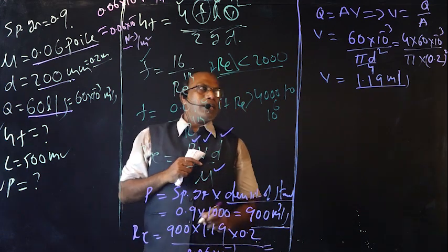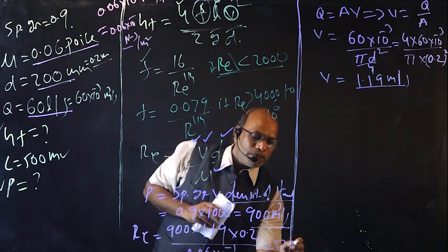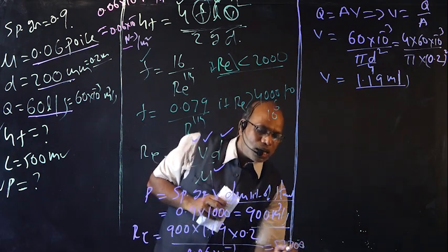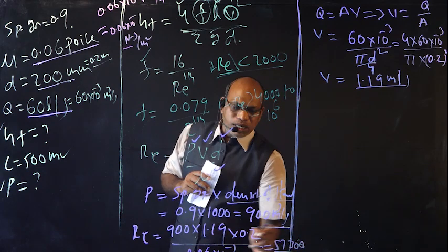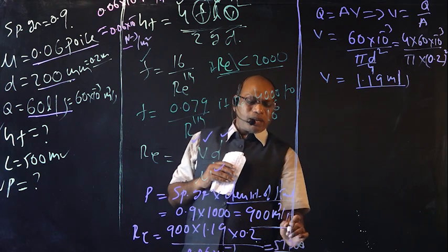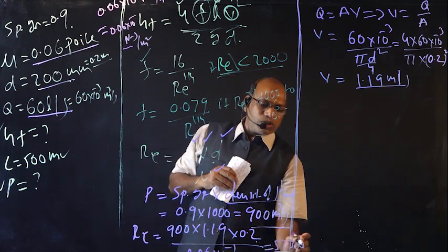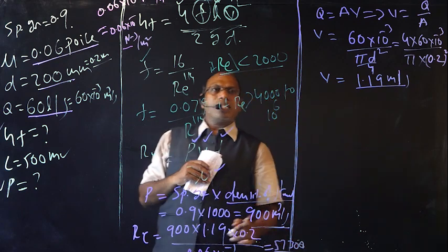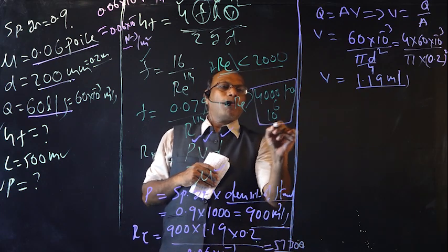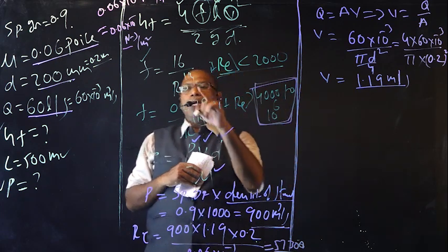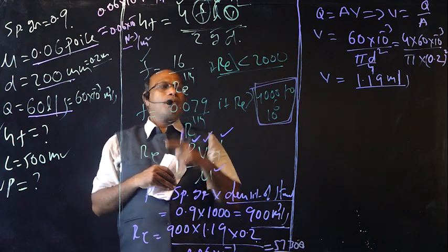Therefore, the Reynolds number is equal to 57300. 57300 is the Reynolds number value. This is a dimensionless parameter. There is no unit. Therefore, this Reynolds number value is in between 4000 and 10 power 6. So therefore, the coefficient of friction is determined by using this formula.